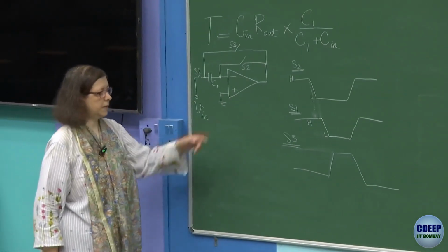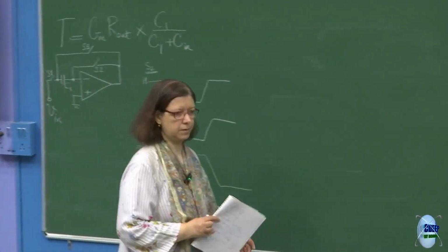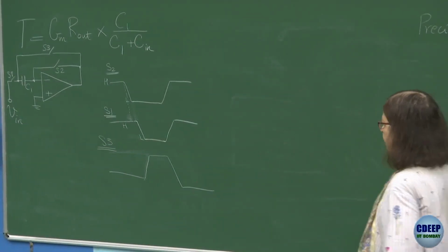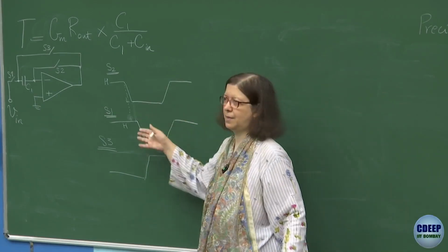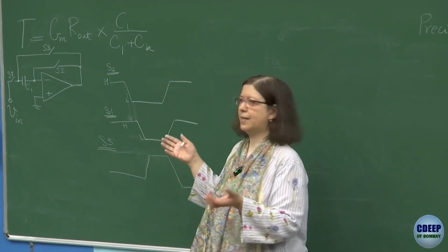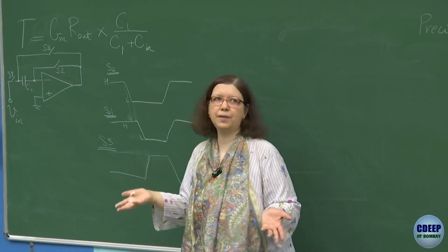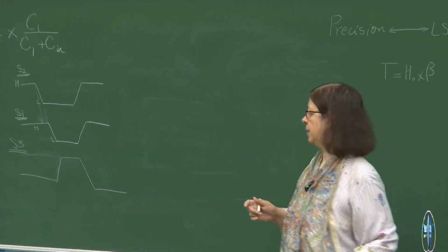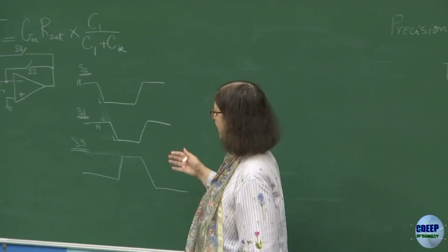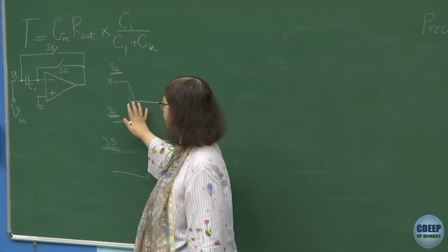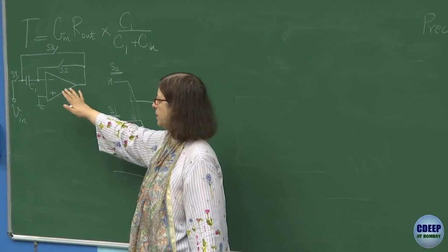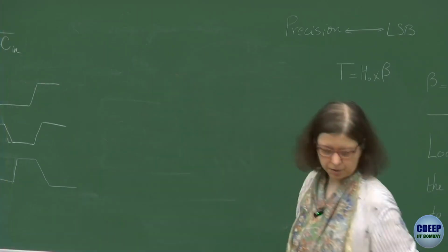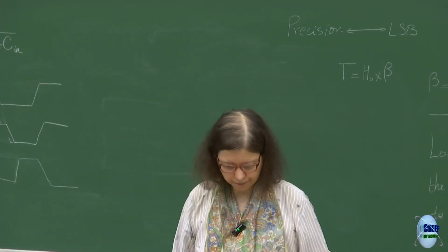But S1 and S2 matter a lot. This is created by adding some delay element. For example, if you make a cascade of two inverters, that may give you a delay element, so that you can adjust the delay to give exactly some delay. This is just to make sure that S1 is turning off when S2 is completely off. So this was about timing, just to show.